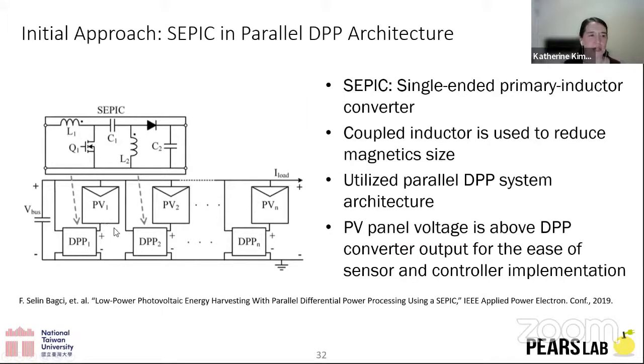When we have these individual ones, it depends on how something would fail. If we have all of them in series, with one converter, and any of the PVs has a problem where they disconnect, the whole thing goes down. And same in the converter. If anything in the converter fails, then depending on how it fails, if it shorts, then you lose all the power. If it fails through, it will just become a PV string. So you would have more points of fault with a single system.